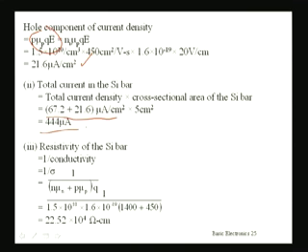And finally the resistivity of the silicon bar, as you know, is the inverse of conductivity. 1 by conductivity gives you the resistivity. Now conductivity sigma is again given by (n mu n plus p mu p) into q. So 1 by this whole term will give you the resistivity, and substituting each of these values we finally get the resistivity of the silicon bar as 22.52 into 10 to the power 4 ohm centimeter.